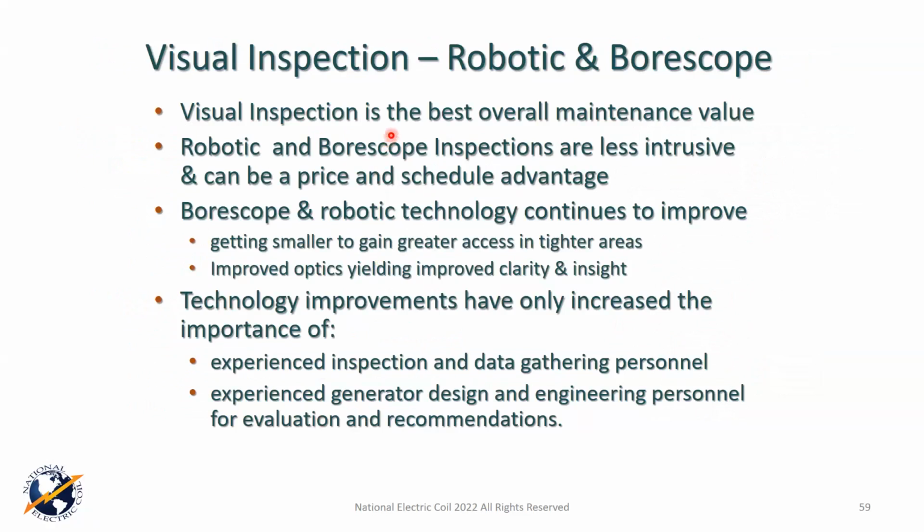Visual inspection has been called the best overall maintenance value you can get, but it really needs to be done by trained and experienced personnel. That's where you get your biggest bang for the buck. But this is still true today, even with technology. The visual inspection is incredible. I talked to you about the borescope improvements in both clarity and color contrast. You can even measure inside some of the best borescopes to close to 1/1000th of an inch in looking in areas. So it's a great technology tool.